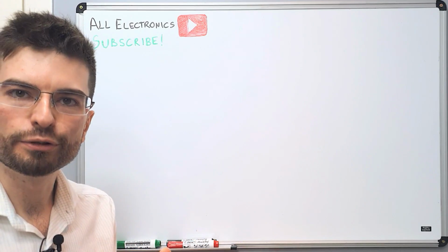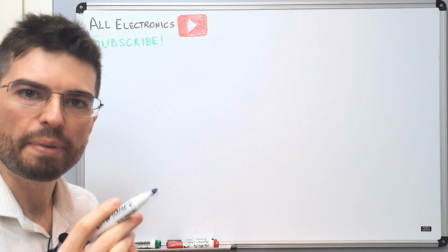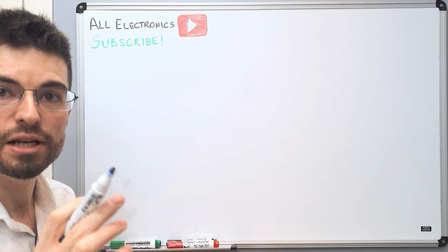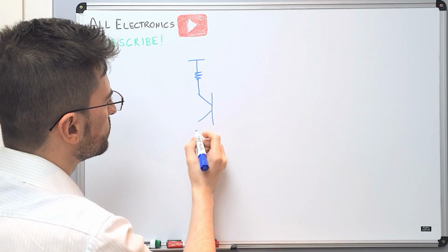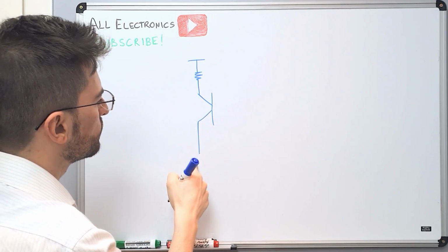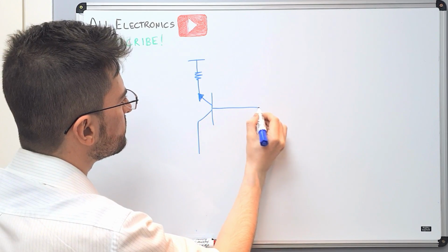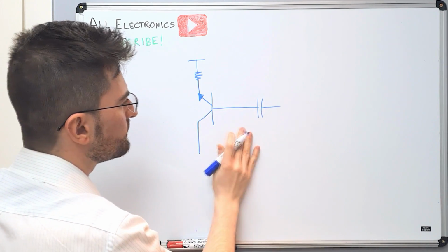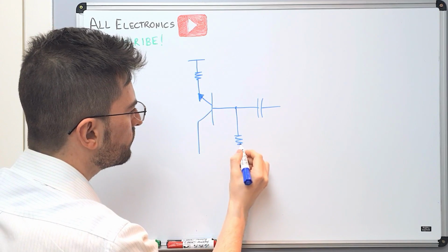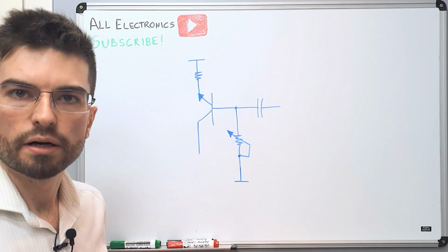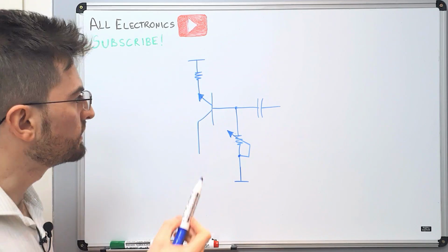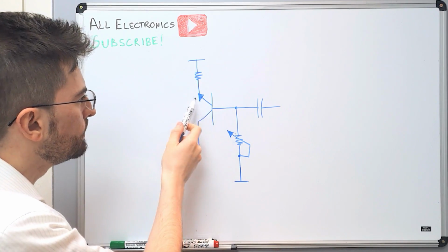The heart of this circuit is a reverse biased base-emitter junction from a BJT transistor. We have a transistor here with the collector unconnected. Here in the base, we extract the noise, AC coupled. We have a trim pot, a trimmer, to adjust the amount of reverse current that we are applying to the base-emitter junction.